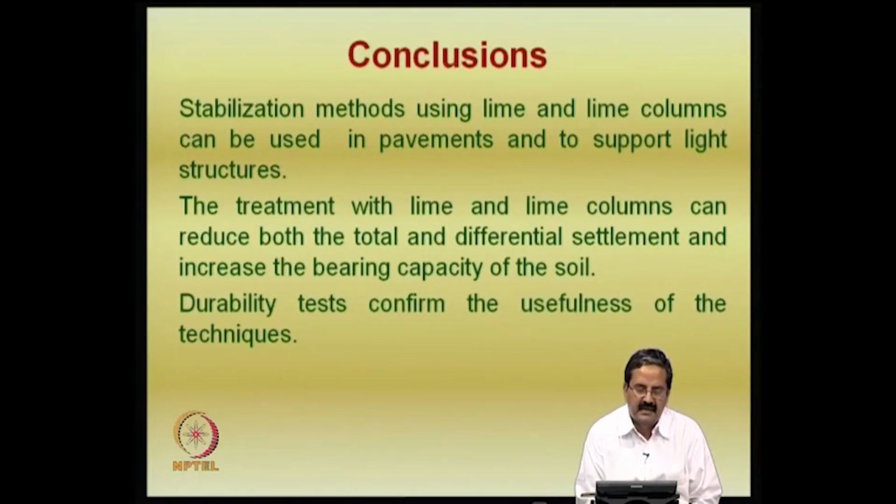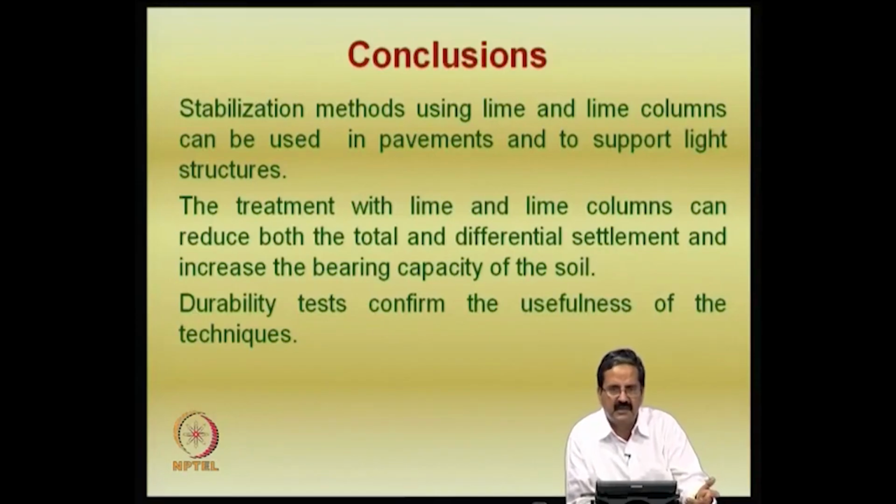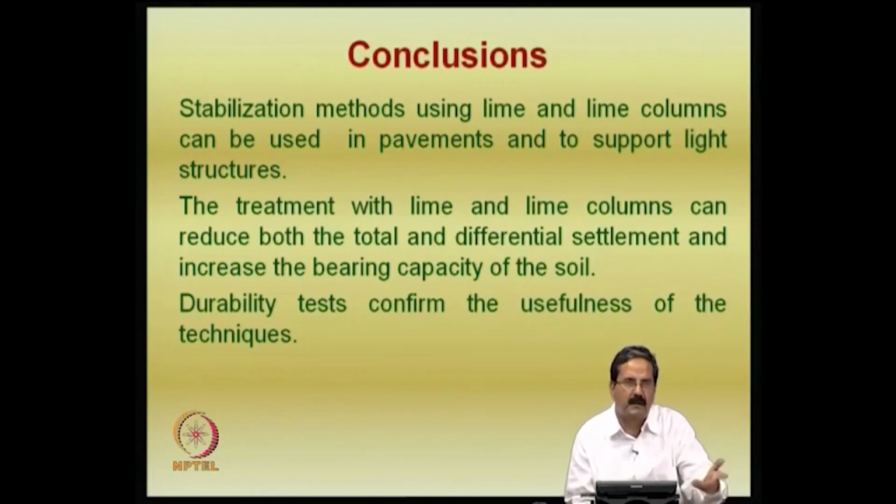So what I would like to say is that for the stabilization methods using lime columns, you should also use some additives if required, though the essential stress is on lime. Here one can use fly ash, as I just used, and one can also use cement, as I just mentioned, to increase the rate of reactions or the formation of the cementitious materials. Cement itself is quite expensive, so why use cement? Use only lime and maybe a little bit of cement. If you are able to get a very good strength improvement based on our calculations and observations, it is satisfactory. You do not need a pile foundation.